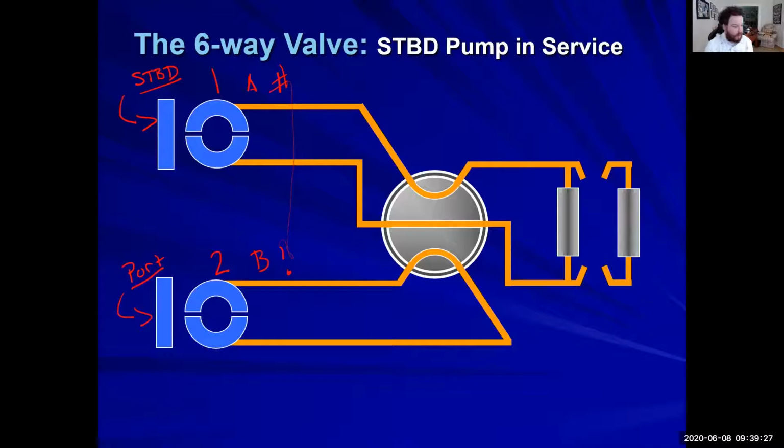The biggest thing I want to get across to you guys is that the starboard pump does not handle starboard rudder movement only, just how the port pump doesn't handle port rudder movement only. They both are axial piston pumps. They both can pump in either direction, and they both can handle moving the rudder from starboard to port and port to starboard.